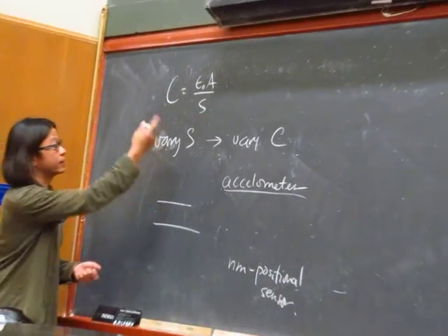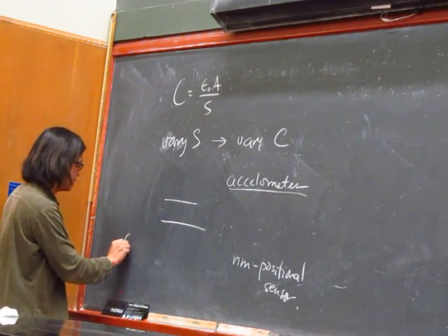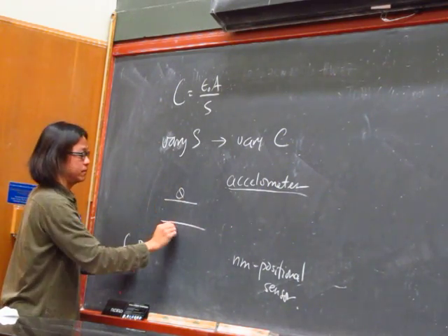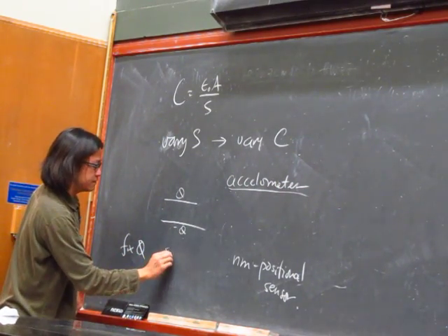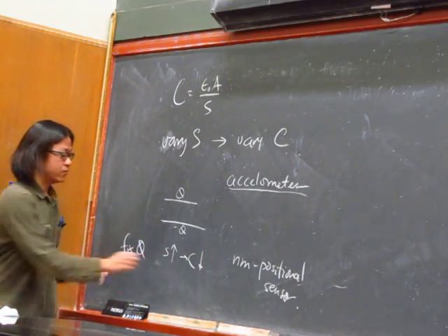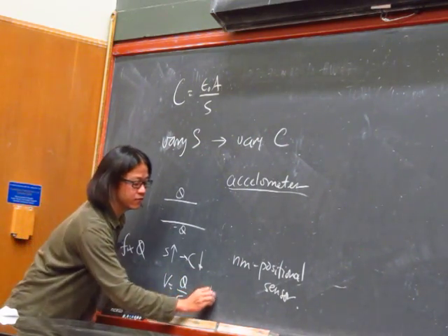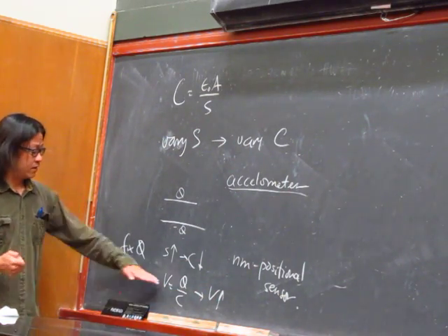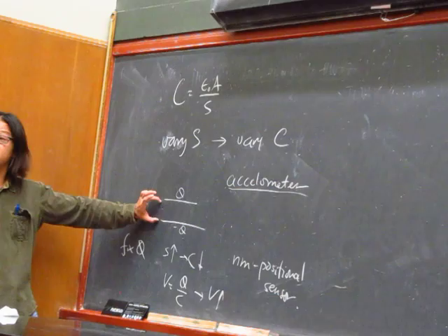Here again, depending on the electronics, you can do it two ways. You can fix Q, plus Q and minus Q here. Then the variation in S leads to a variation in C, and since the voltage is Q over C, you have a variation in voltage. And you measure that variation. By measuring the variation in voltage, you know the distance change.